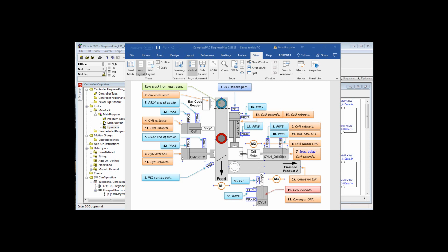The first thing they really encounter, even though they do move into the scan zone for the barcode reader, your system, our control system, does not sense or know anything's there until PE1 senses part. So when that part interrupts the optical path of photo eye 1, then our system basically says, aha, we've got a part coming in.